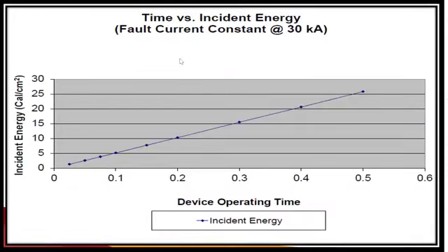So from the exam point of view, we also have to keep in mind that the available incident energy is dependent on the device clearance time, provided that the fault current is constant at that particular location. We can also see this graph from another angle.